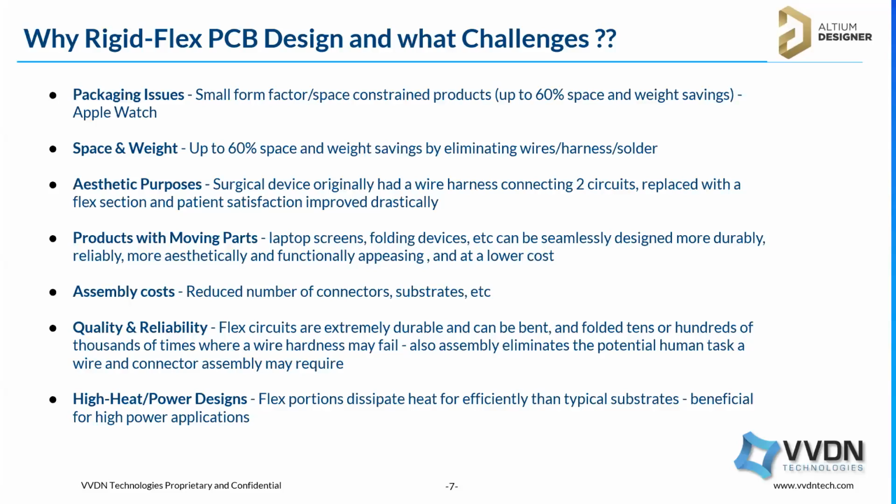Flex circuits are extremely durable, and they can be bent and folded tens or hundreds of thousands of times, where a harness may fail. Also, it eliminates the potential human error of wire and connector assembly. At that time we can use this design.